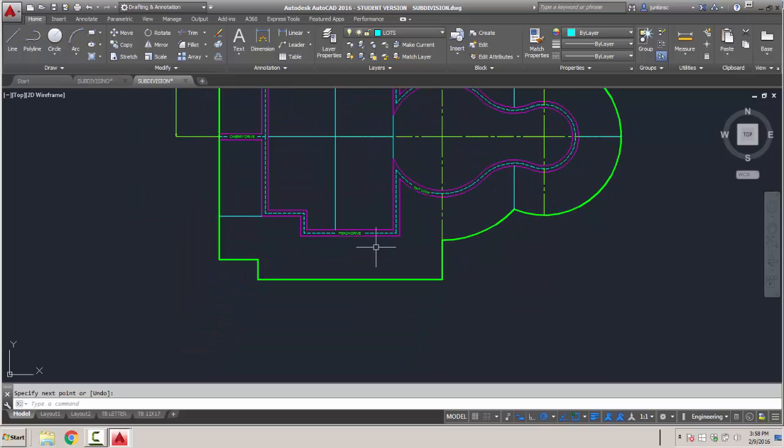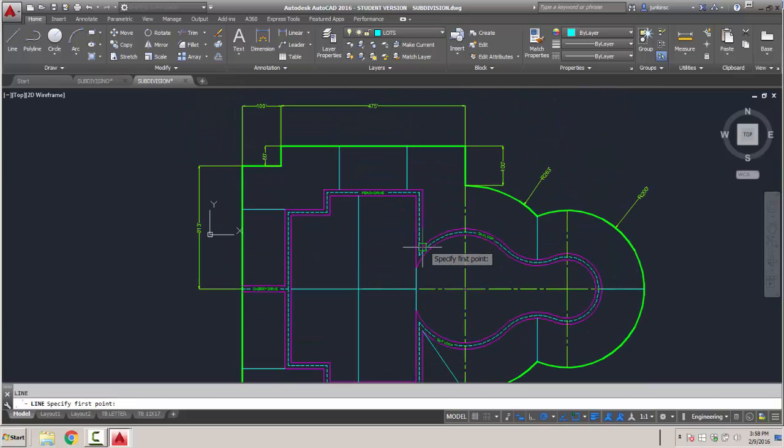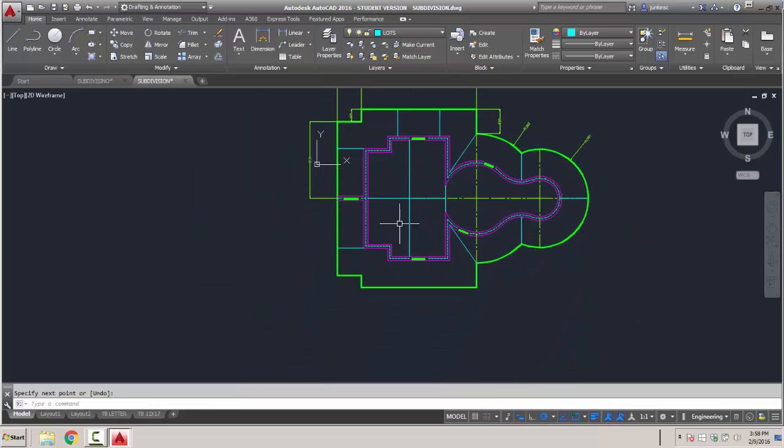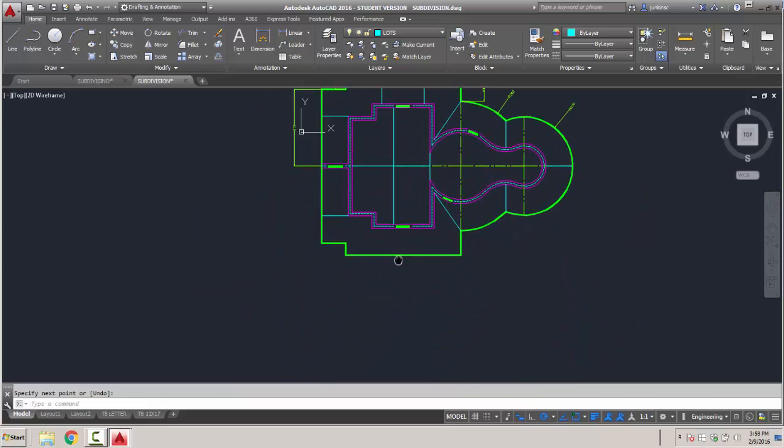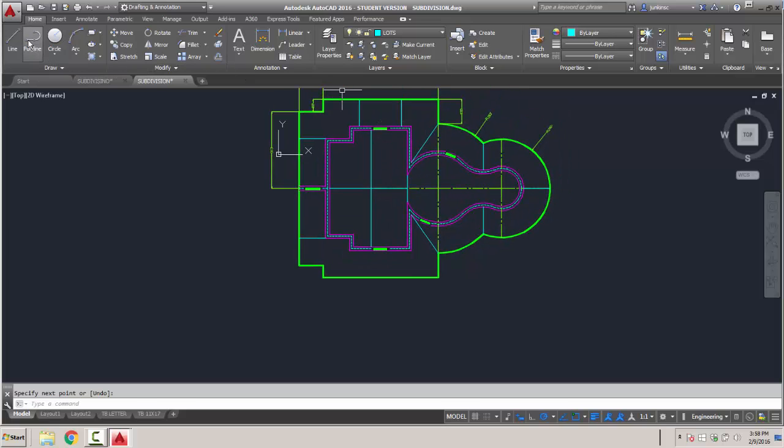Then we've got a line that goes from this vertex to this vertex, and it mirrors it on the other side. And now we've got 2 lines that actually line up with these 2 lines on the top. So if you want to be lazy, you can just let it click right there until you see endpoint and just pull it straight down. You see how that dotted ghost line comes up? When I get through these, just left click and then go down until it finds, whoa, hit the right mouse button by accident, sorry. Left click, get out to perpendicular, right click and start it here, just let it settle, bring it straight down, find that point, left click, and then bring it down until it touches.